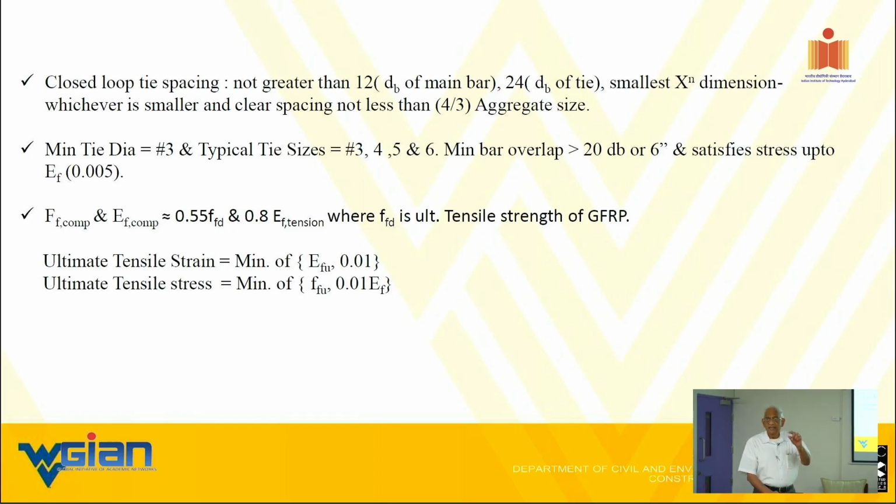Therefore, what they report as guaranteed for you is 0.8 times that average. So you see, that's the second one. And the third one, when you're ready to design, you multiply with the CE factor and other reduction factors. So you don't even know what the average value is. What you know is the average minus 3 sigma value.